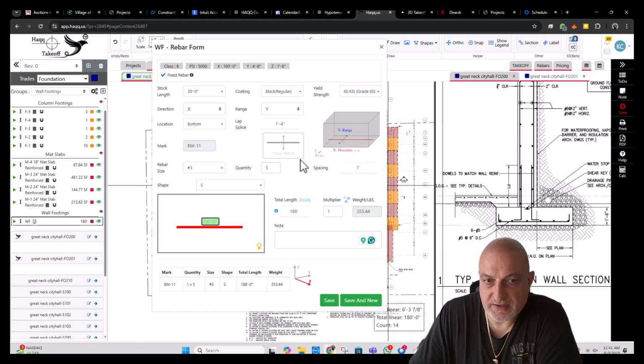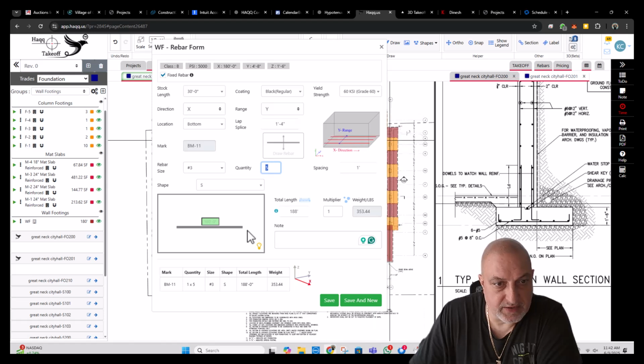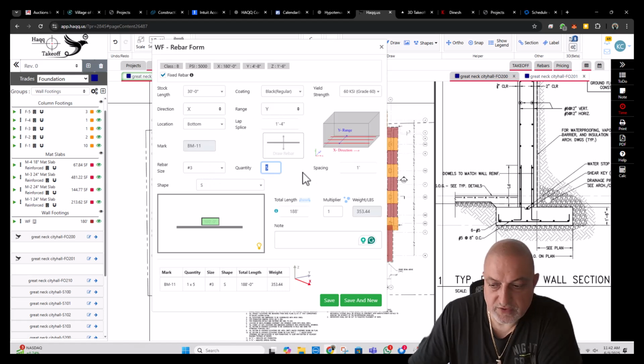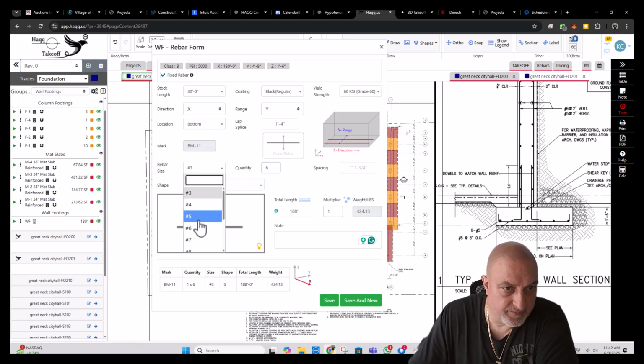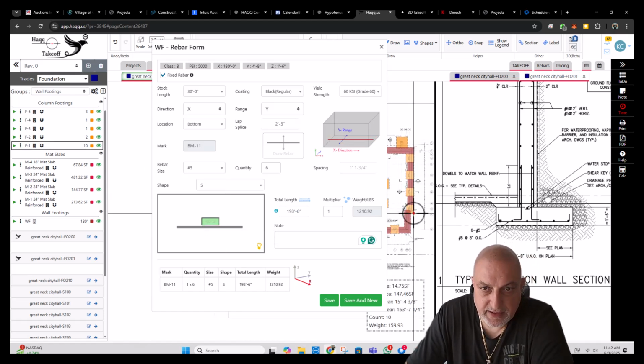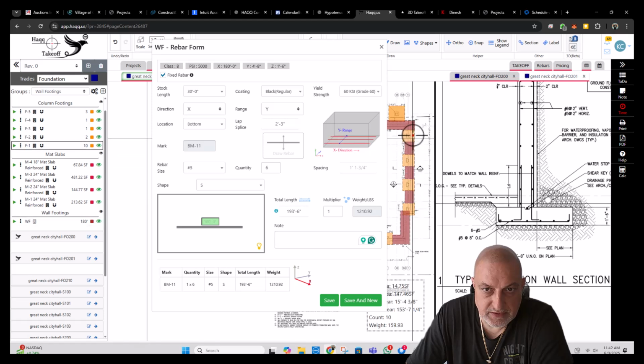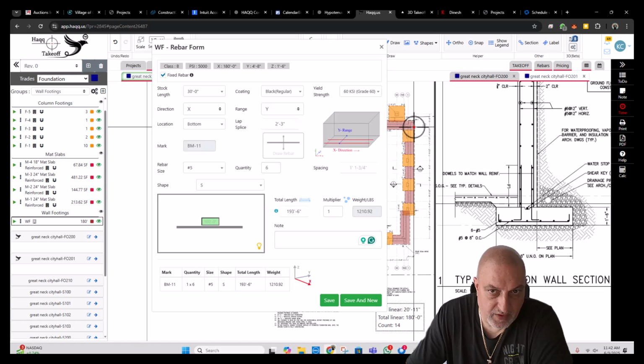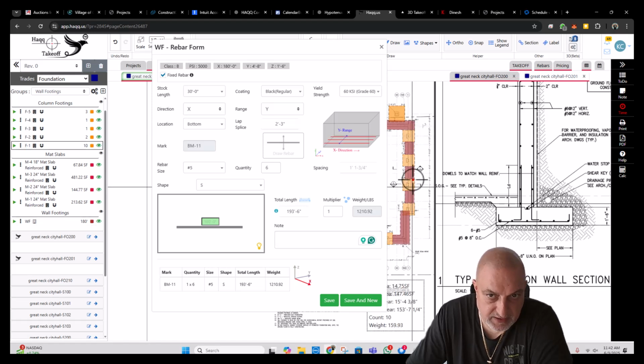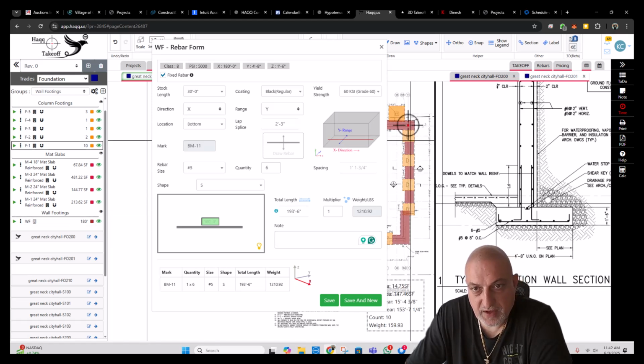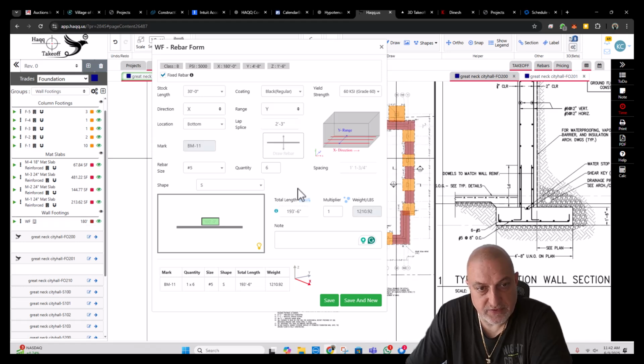Okay, here's the thing. We got 6 bars. It shows already the length wise, which is 180 feet. So we don't need to change anything up there. And the bottom bars, we just do 6 number fives. But this is not including all these column footings. But the way it works is, at the job site, that's how rebar shop drawings are done. We have to continue through the column footings.